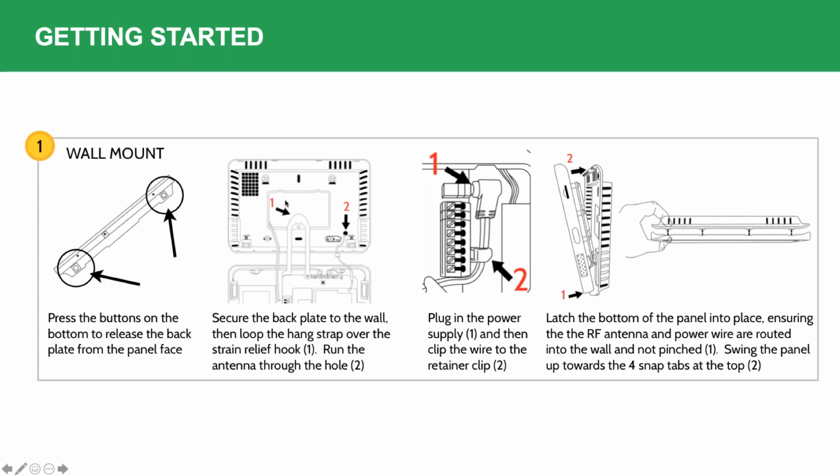We've seen that just going out this back plate, going over a couple inches and smashing that antenna against a board, you can lose 30% of your range. So make sure you're routing it out that hole, getting it away from that little rock concert of RF that's happening up above with 900 megahertz and the cell unit. Then you'll connect in your barrel jack for power. You can route it behind this retaining clip, and then you'll close your panel.